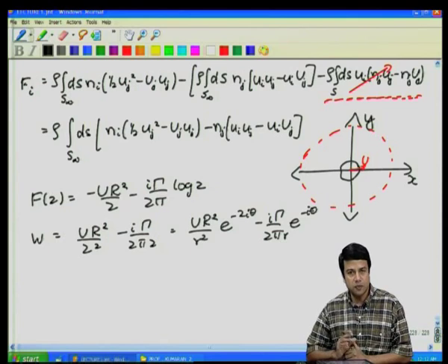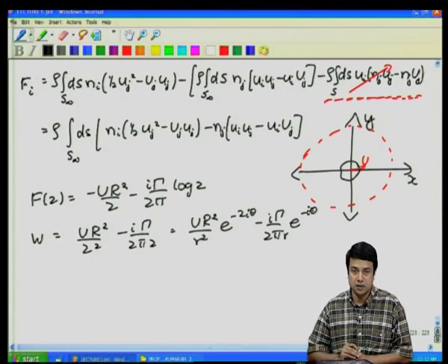So, these are the two components of the velocity, due to circulation as well as due to the mean flow, due to the flow of the object with velocity U as well as due to the circulation around this object. You can see that the velocity decay due to circulation, due to the line vortex, is proportional to 1 over r. Due to this constant velocity, it is proportional to 1 over r square.